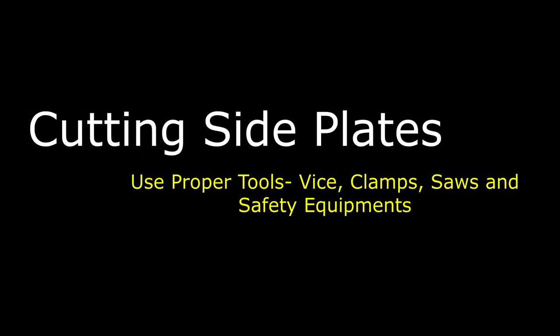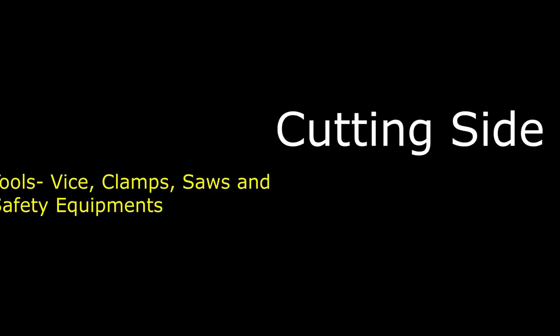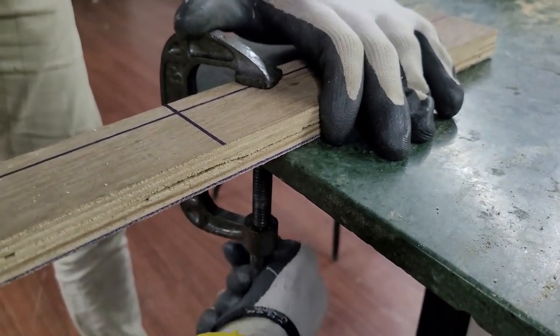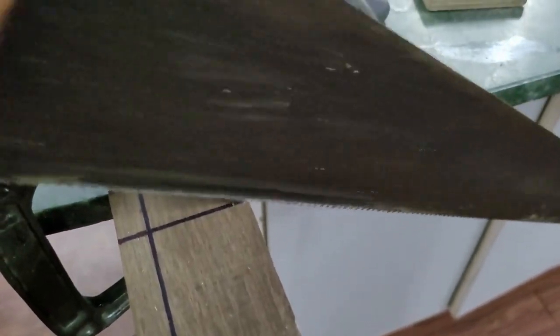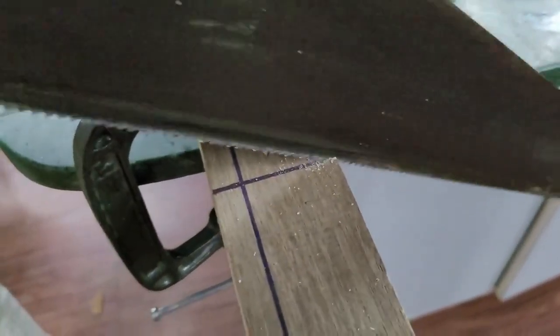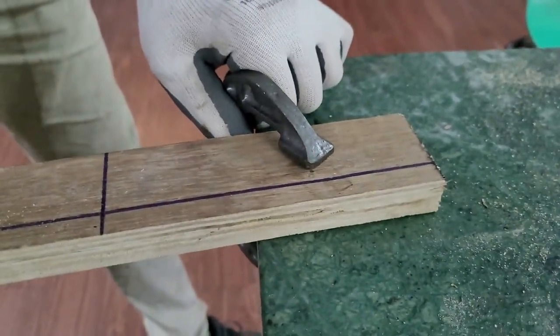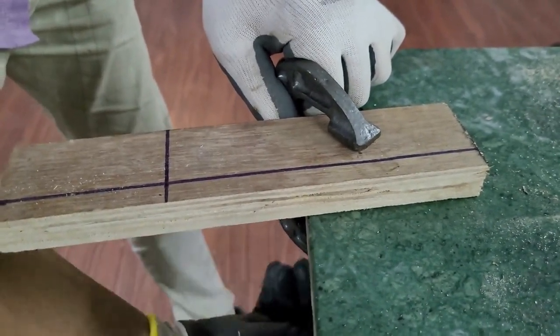Now let's cut the side plates. So use proper clamps again, and saws and safety equipment. Clamp the side plates using the C clamp. Cut along the marked edges. Use this type of saw or hacksaw with frame. Cutting it at 150 millimeters. One plate is ready. Now cut the second plate.